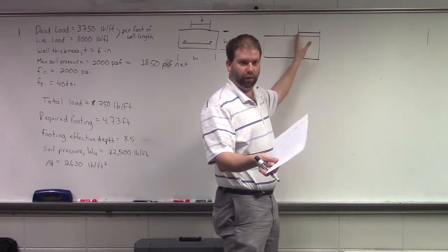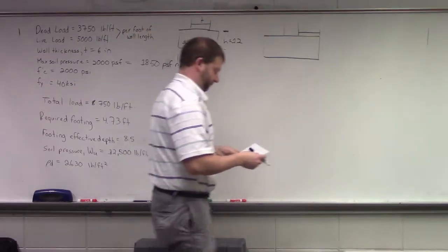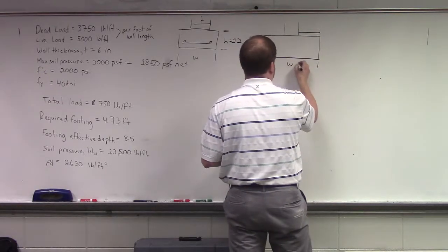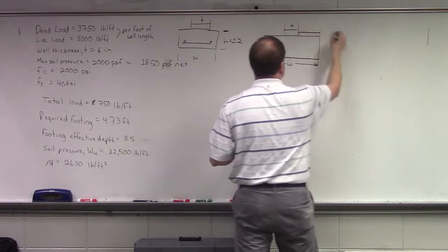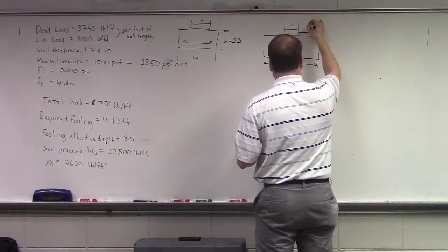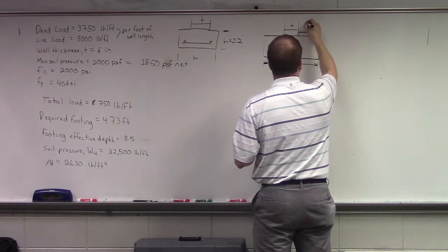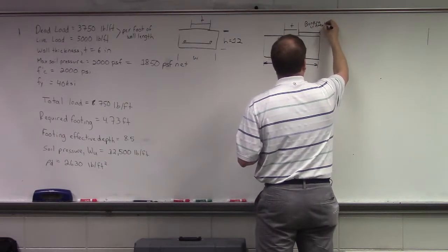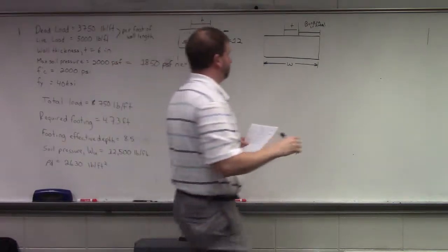And Rush, do you remember what it was that you pointed out that people could do? You said the W minus the T, because where you have the T, so width minus the wall thickness, divided by 2. So W minus T divided by 2. And that gives us our critical dimension for bending.